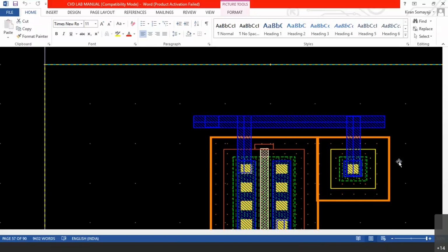As that diode should never conduct, even for leakage current it should not conduct. So what do we do? We reverse bias the diode by connecting it to VDD, in case of P MOSFET. So N region is connected to VDD so that the PN diode between substrate and well remains reverse biased. So you can see this is also a via. What type of via? N well to P substrate via.